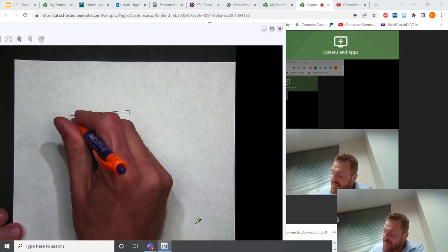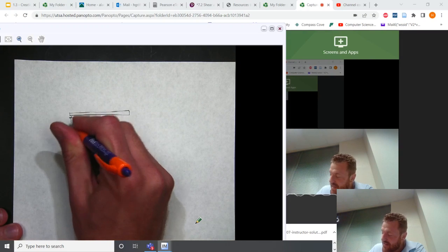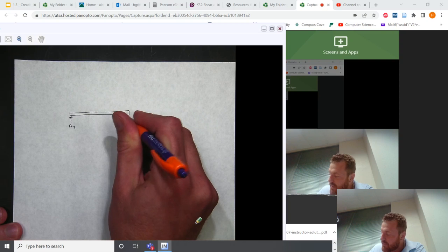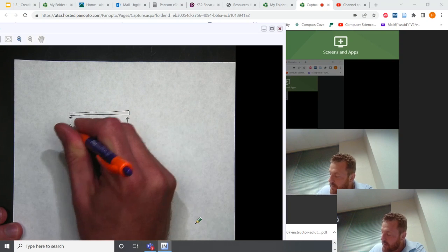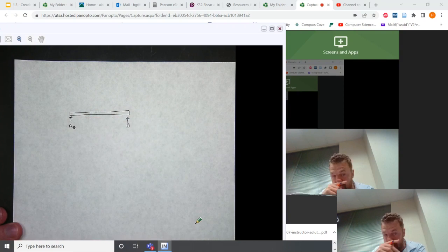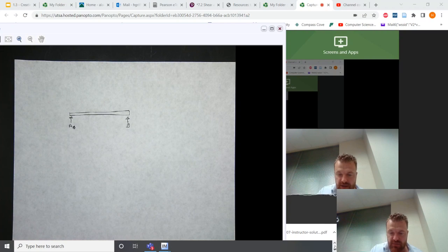to start from scratch. So I'm going to draw in vertical reactions on both ends of the beam, and I just call them A and B. I'll take off the Y because, again, as we mentioned, this could have an X component, but it doesn't need it. In addition, I need to, from the perspective of solving for my external reactions, replace that entire distributed load by a single concentrated force.